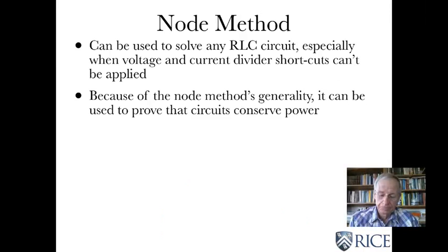All right, so the node method, we can solve any RLC circuit using it, and it's especially used when voltage and current divider shortcuts can't be applied. As we start talking about electronics, you'll see there's a really good reason why we need to talk about the node method. And like I said, it can be used to check your answers.